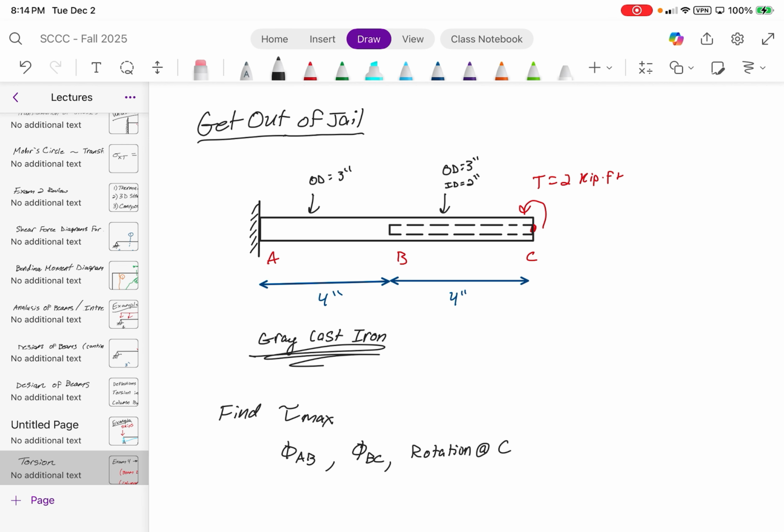Inches times 4 feet divided by 4,100. Keep in mind, 24 is in kips, you're using 4.1 times 10 to the 6, which is PSI. So now you're using radian kip per pound. Consistency in units is key. Units. I think that's where I take the most points off throughout the entire semester, is units.